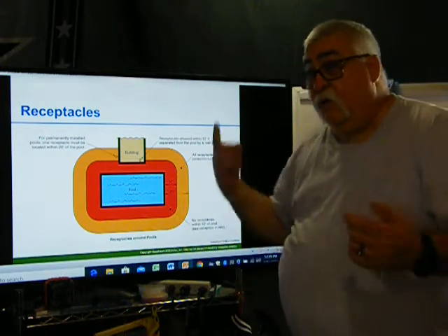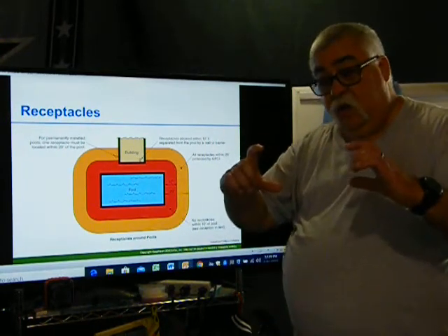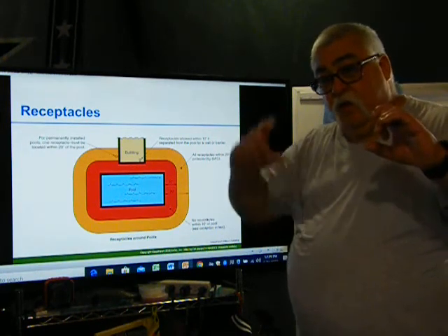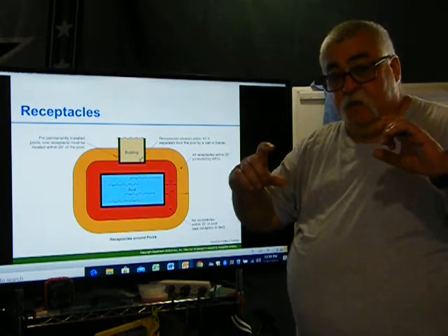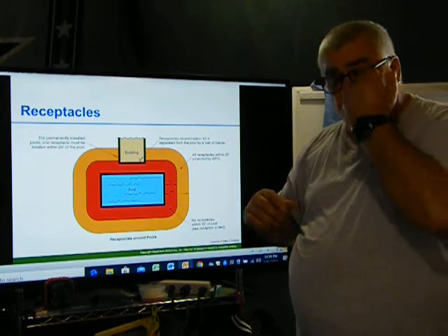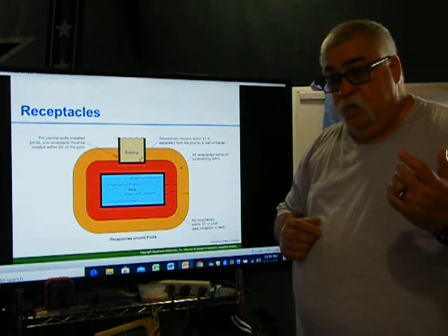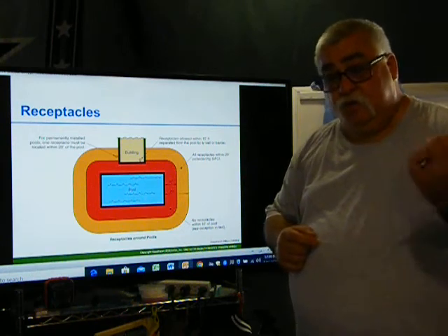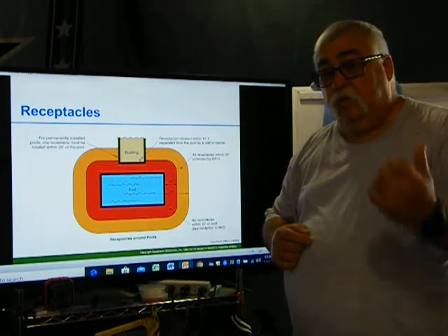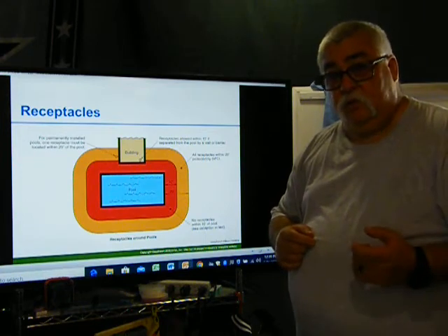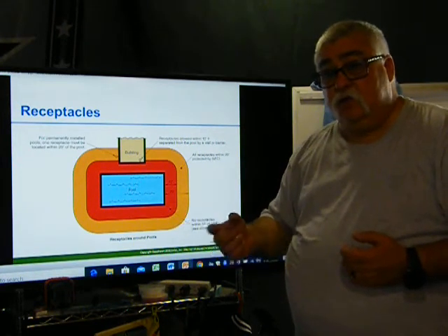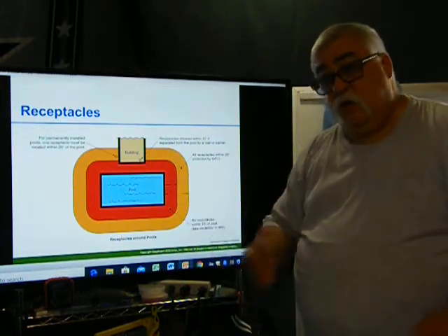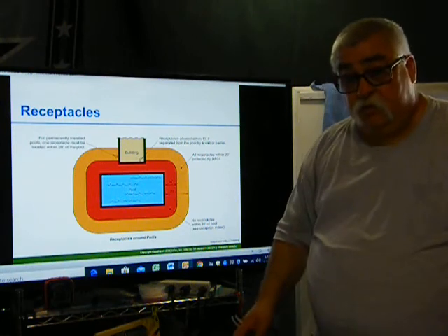I usually put a 20 amp. I have a gas furnace, so I have a 2-gang box. I have a switch with a switch receptacle and a duplex right next to it. Okay, so I have a circuit coming in for my furnace up to 20 amps gas, and I feed the switch. Off the switch it goes to the receptacle, so when you turn the switch on, it turns the receptacle on. That switch receptacle is a 20 amp switched receptacle. Okay, and then right next to it is a duplex that I just picked up a circuit off of the general lighting in the house and ran it across for that duplex receptacle, so it has nothing to do with the furnace.